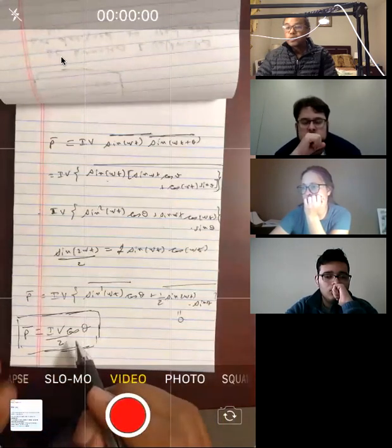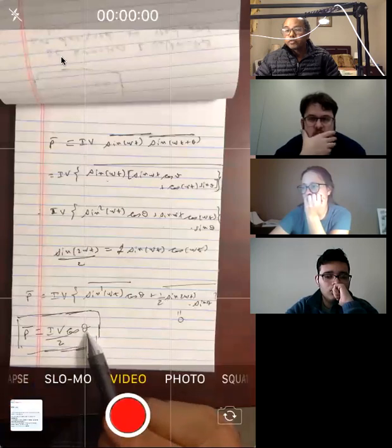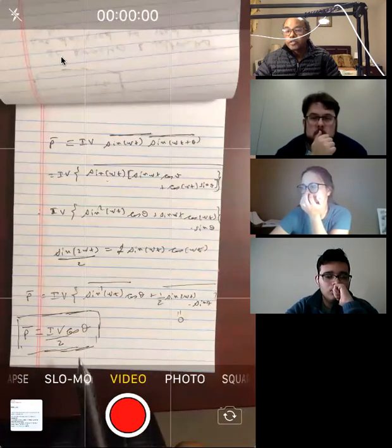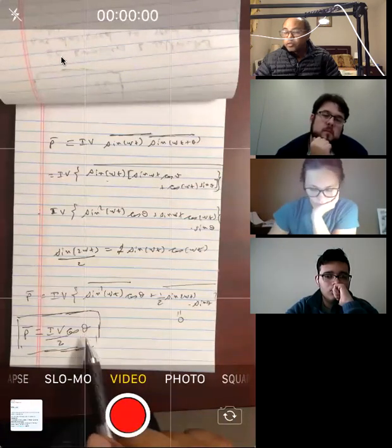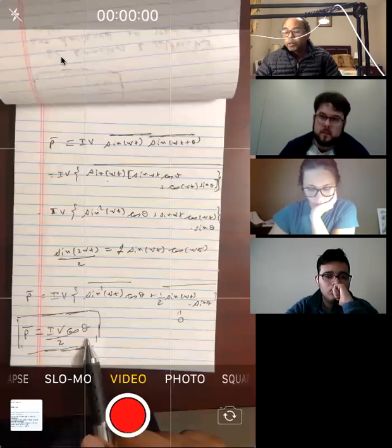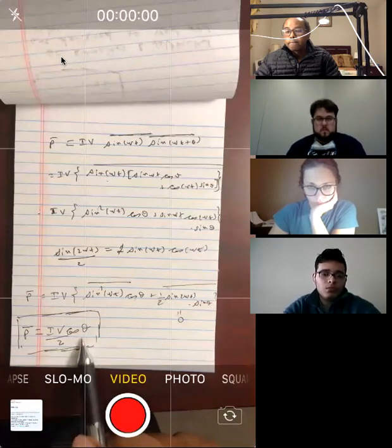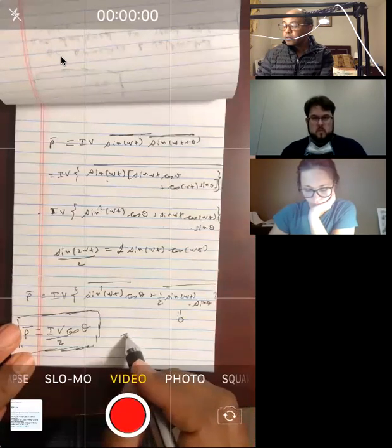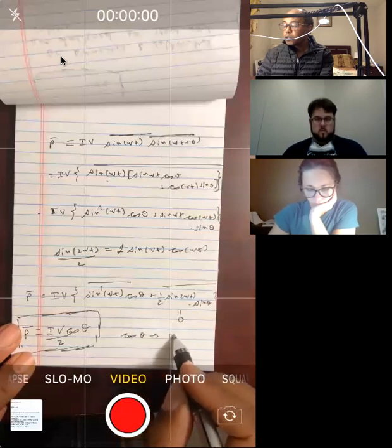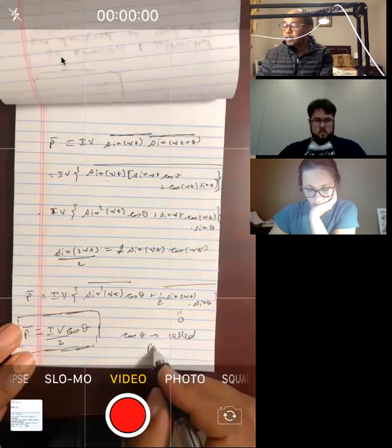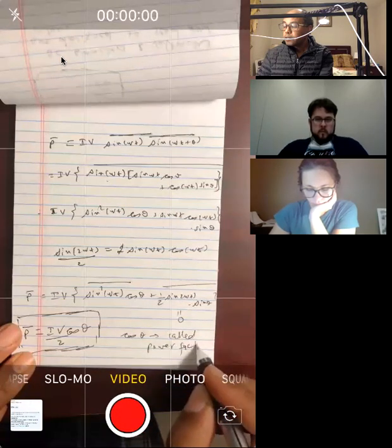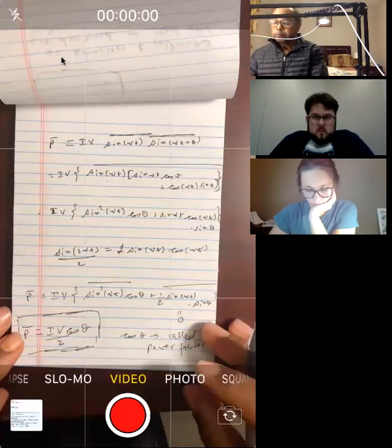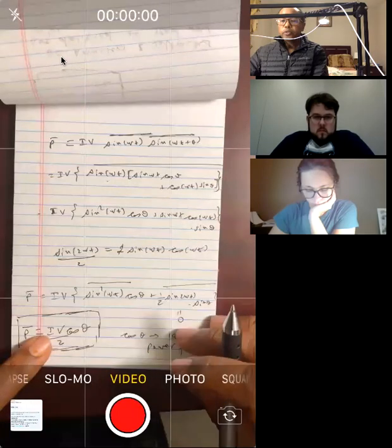You see, this phase shift angle is very important for engineers, because how much power you get from the circuit depends on this angle. If it is pi over 2, you don't get any power because cosine of pi over 2 is 0. The expression cosine of theta is called the power factor by electrical engineers because it determines how much power you get from a circuit. Now let's write this in terms of RMS values.